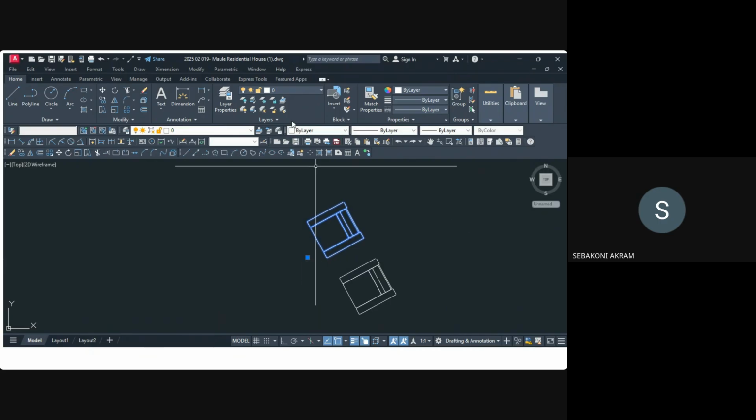So when I change this block to grid, let me say to grid layer, pardon? Yeah. If I change this, to the grid block, this chair to grid block, it's now grid. Are you seeing? It's grid. But however, if I go into its initial parts of the chair, they are not at layer grid, they are at layer 0, the original one.